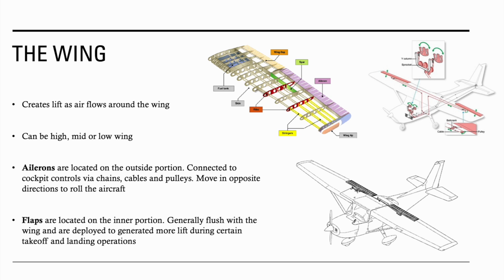I think Piper has manual flaps, so it kind of looks like an e-brake, if you guys have ever driven manual. It's in between the two seats and it just looks like a big e-brake. Whenever you move that lever, it moves your flaps. The downside is it's a lot of work to move those flaps, but it is more instantaneous, whereas with electronic flaps, you have to wait for the motor to kick in, and it's a very slow deployment and slow retraction of your flaps.